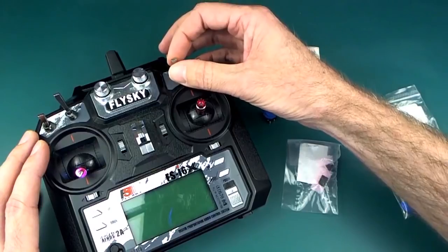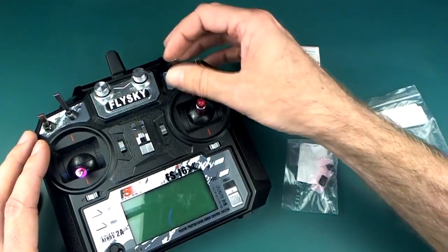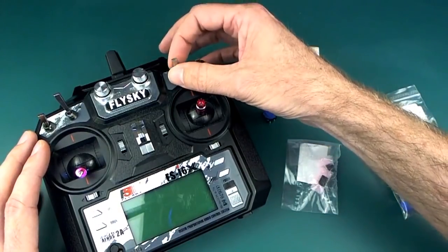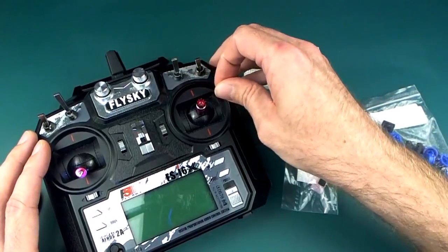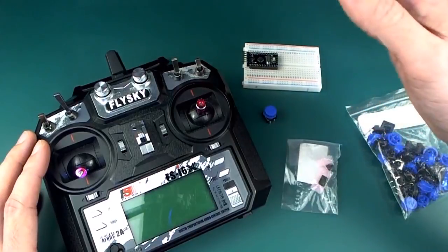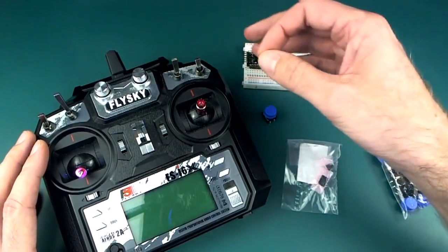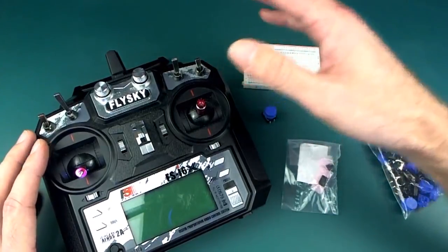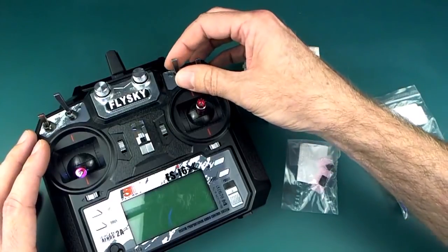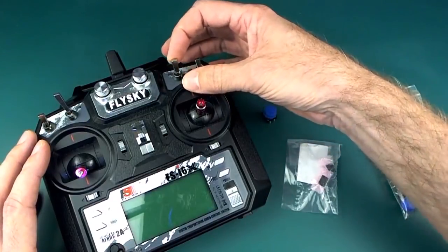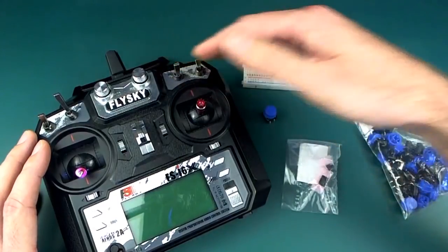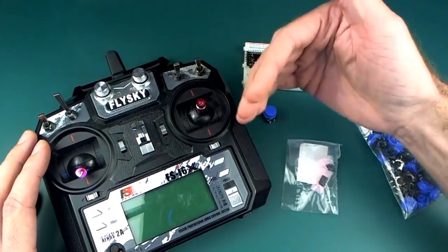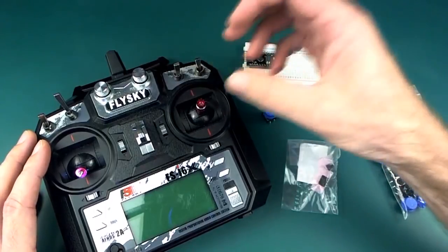Anyway, so that leaves me with just this one position in the middle to do what I really wanted to do with the plane, which was usually fly-by-wire A, but sometimes it's auto, and quite often I just want to do something like take off my jacket or find a nicer place to sit down, when I don't want to keep my eyes on the plane constantly. Usually what I'll have to do is put it into return to home to do that, which can be a bit of a nuisance if I'm flying further away and I didn't really want to return to home. All I wanted was to have it loiter there for a bit.